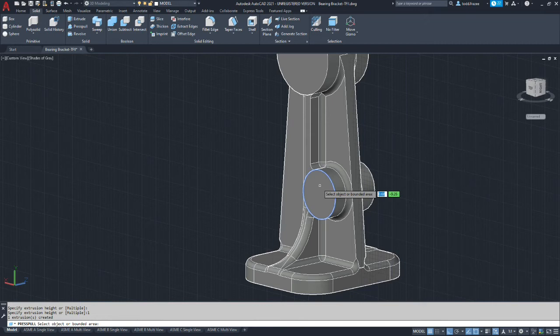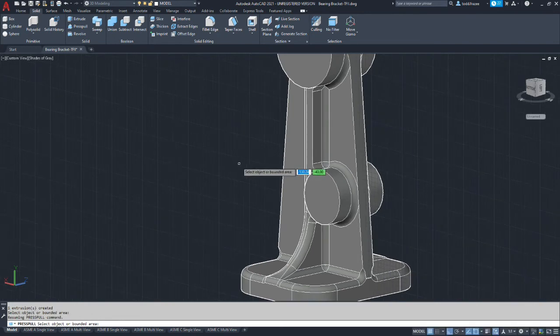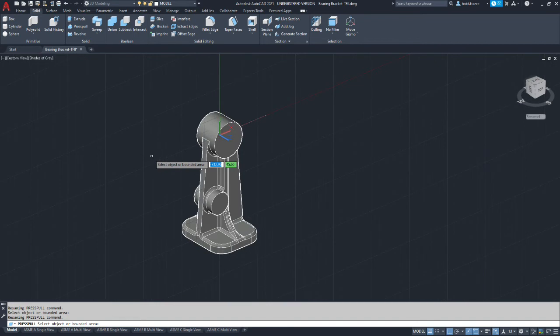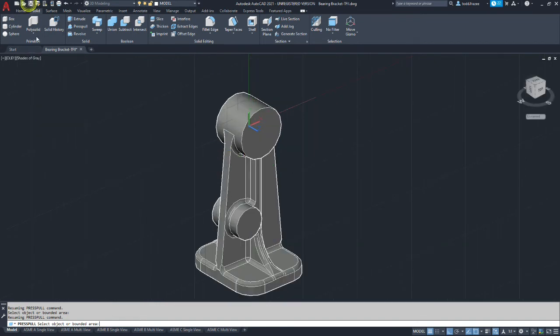So if we measure from the face I've highlighted to the opposite side of the boss, it should be a total of 33mm. Make sure you do it on the correct side, because that's going to be something that needs to be called out on the drawing. Okay. All right. Let's save, and we're going to next put the boss on the top of the part, and that'll be the last additive feature. Everything else we'll do is subtractive at this point.